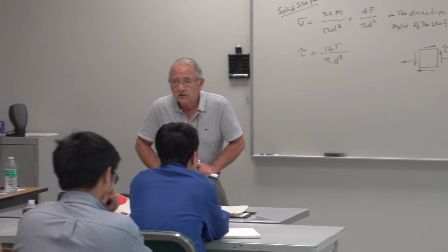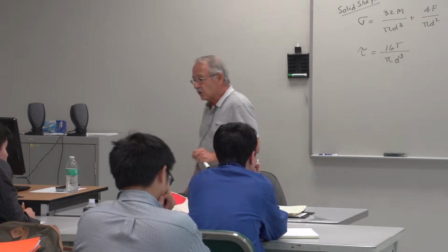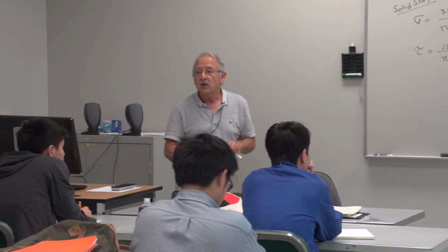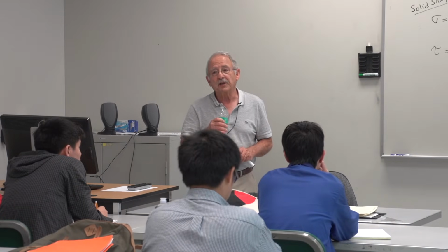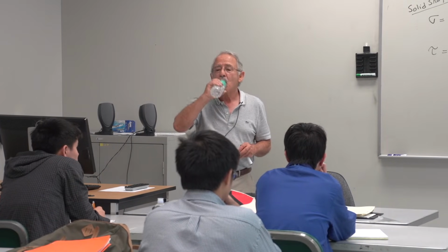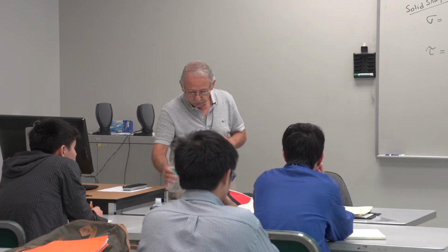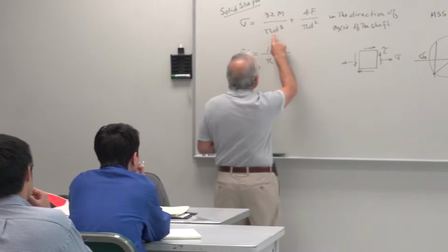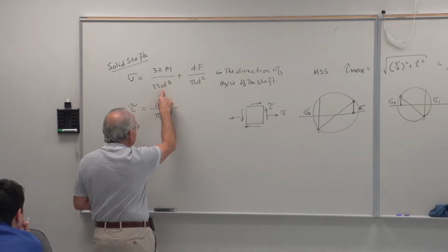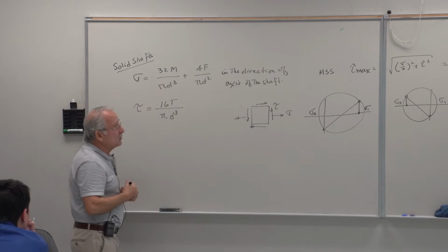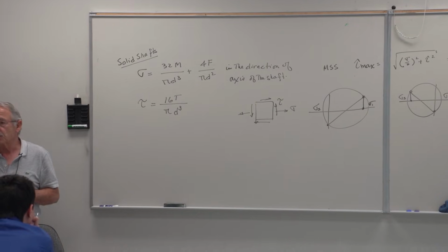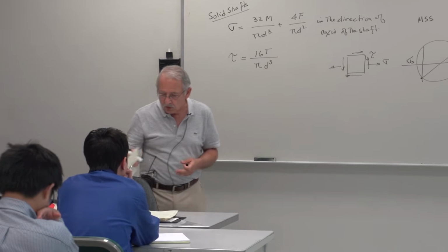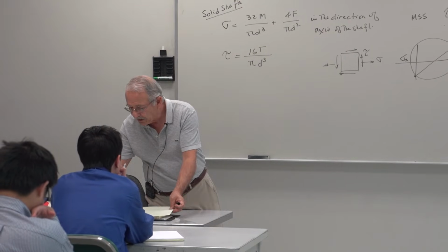In many instances, the axial stress that is generated in the shaft is much, much smaller than the bending stress. So this is generally much, much smaller than that. So many times we neglect the axial stress and we just bring in the bending stress.